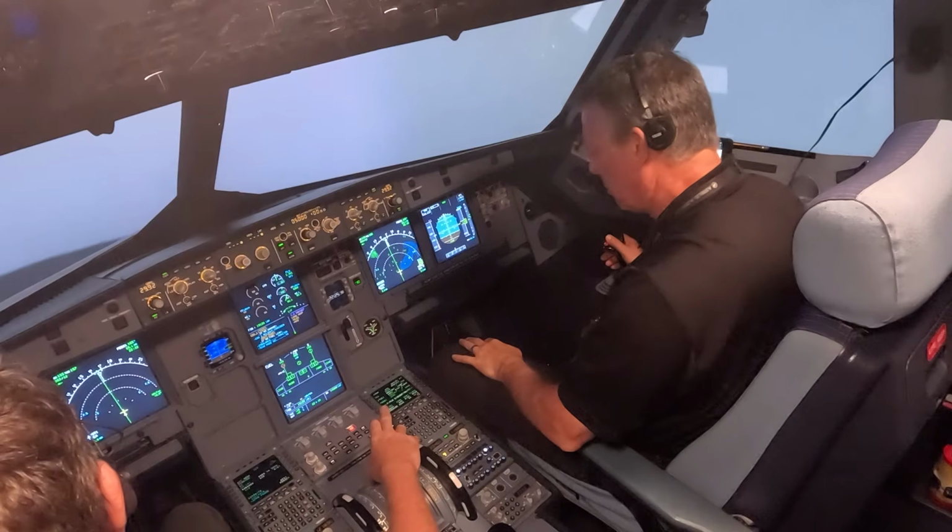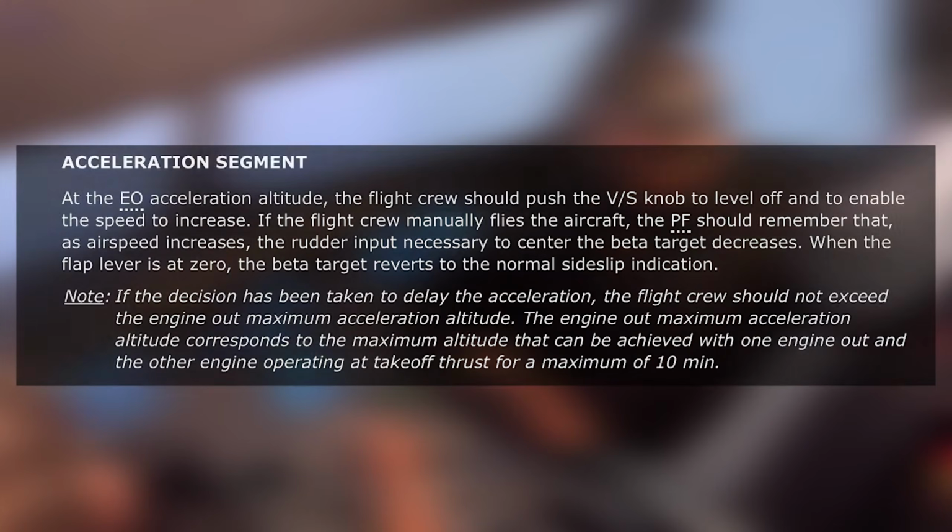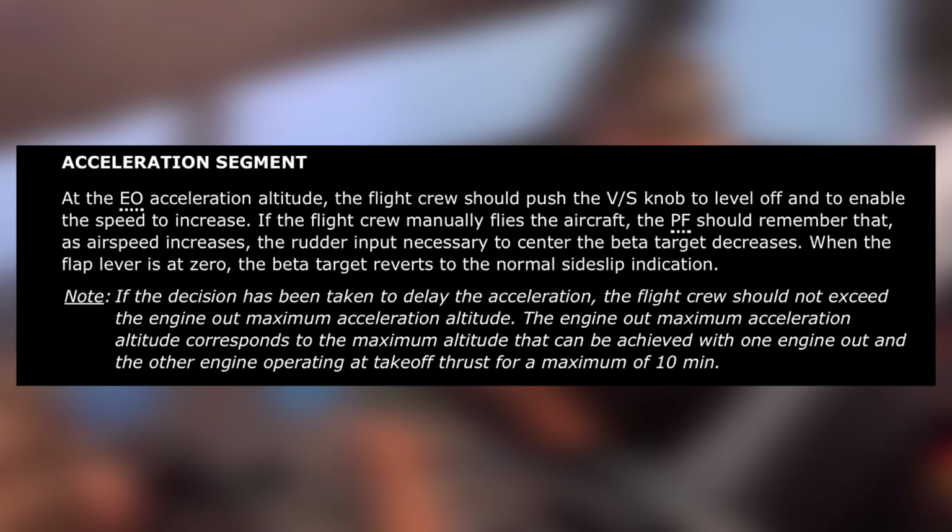Vertical speed 0. There are two occurrences happening at the same time here worth mentioning for both pilot flying and pilot monitoring. The aircraft has reached the engine out acceleration altitude. Note that Neil pushed the VS knob to level off and allow the aircraft to accelerate. If flying with the autopilot off, which is not the case in our video, the acceleration makes the rudder more effective, meaning pilot flying would have to retrim the aircraft.